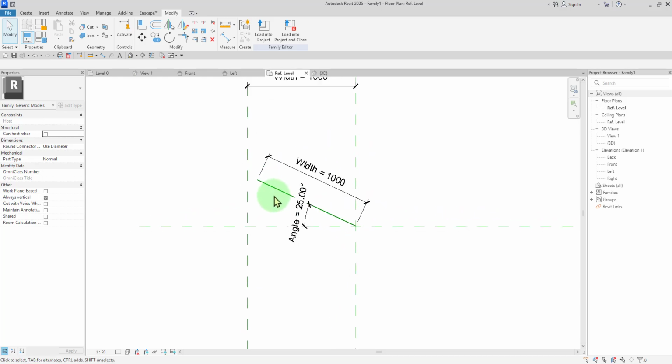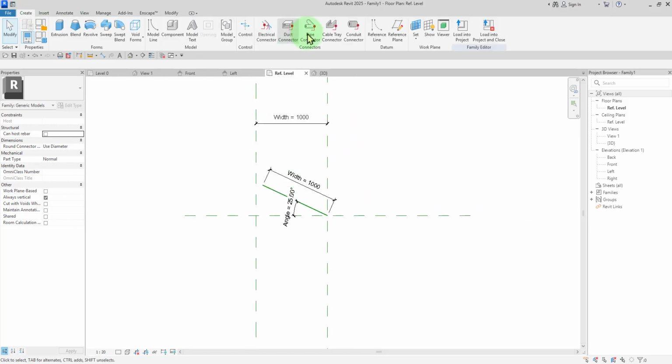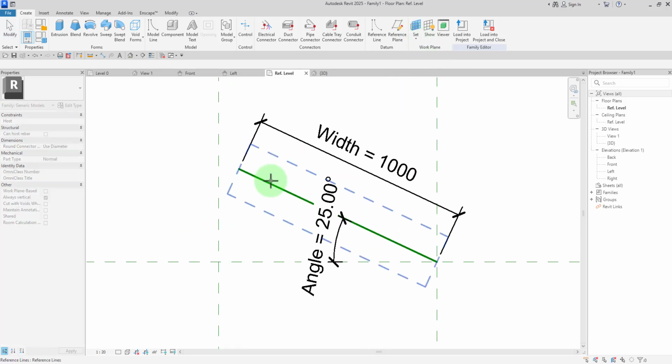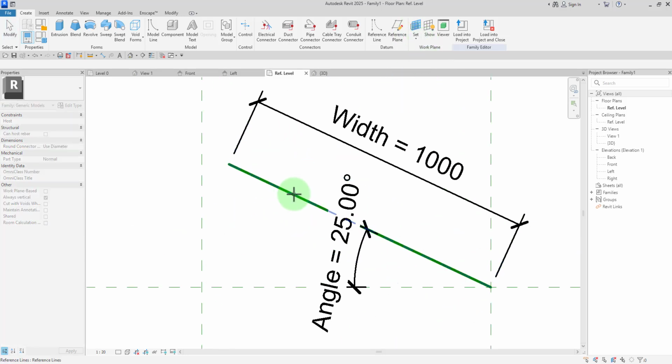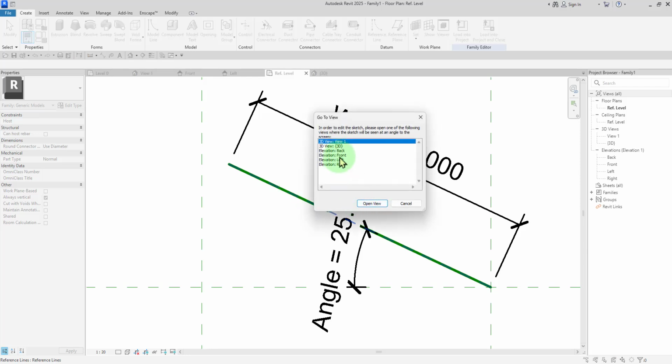and we are going to draw our door. So we need to head into the create tab, and then just click on this set right there. Click on the drop down menu under the set tab, and then make sure you click on pick a plane. All right, so move it in there, and then just hit the tab key to select the reference line. All right, selected. And Revit is not going to allow us to draw this in this view, so we need to find an appropriate view.